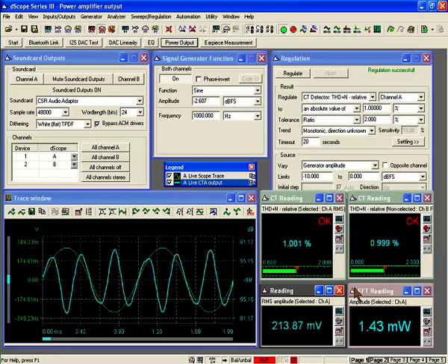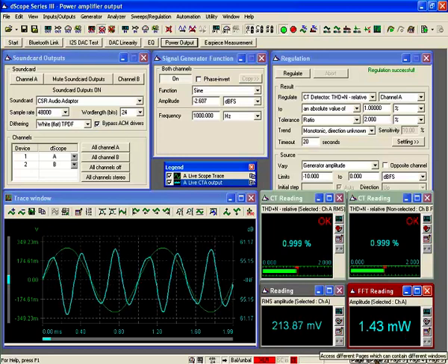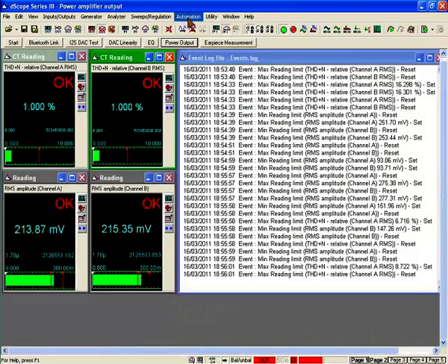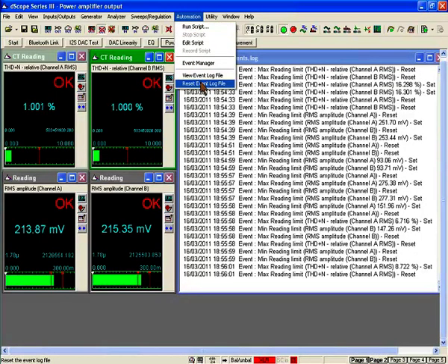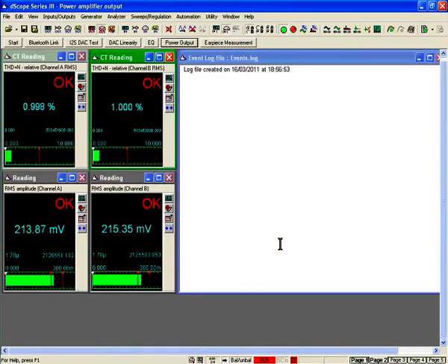And because we're measuring a power amplifier here, we now want to quantify that in terms of electrical power. So Dscope has interpreted this as 1.4 milliwatts, accounting for the 32 ohm load that this voltage is being driven across. One thing you might want to do is to check whether your power amplifier has been correctly designed in terms of the thermal relief, and you might want to monitor this over a period of time. So once again, we're going to use this very powerful set of tools in the Dscope that allows us to monitor a wide range of results over time.